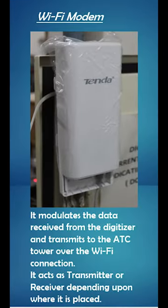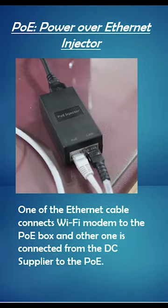The Wi-Fi modem modulates the data received from the digitizer and transmits it to the ATC tower over the Wi-Fi connection. It acts as a transmitter or receiver depending upon where it is placed. PoE is a power over Ethernet injector. One Ethernet cable connects the Wi-Fi modem to the PoE box and the other is connected from the DC supplier to the PoE.